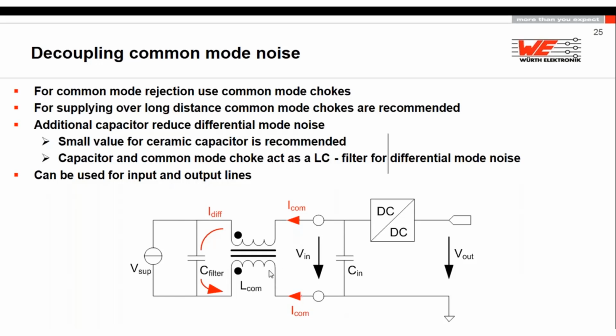And beginning from this point, the common mode choke is just a heavy component on your PCB. It's good for the kilo, but it's not good for the EMI. You go inside of the PCB with the common mode choke, and after the common mode choke, you declare this is your own clean ground. It has a galvanic connection to the output, but only through the coil. Everybody in your device must talk to this leg of the common mode choke. It means to its pin, the same ground point.